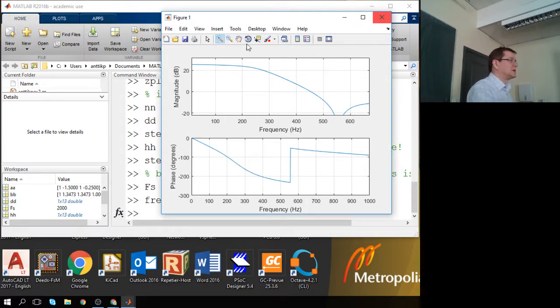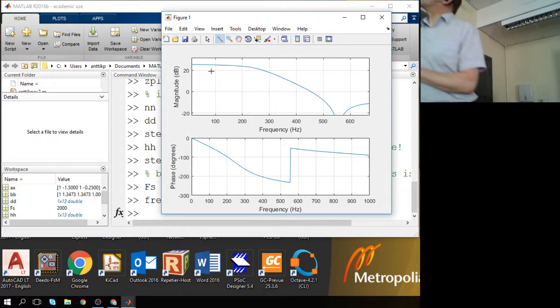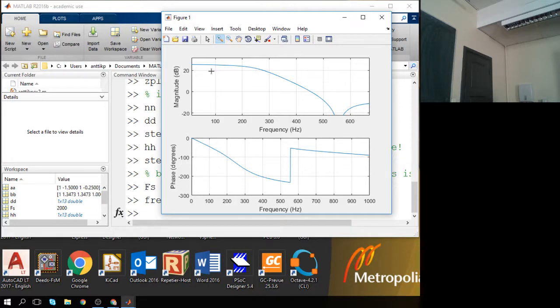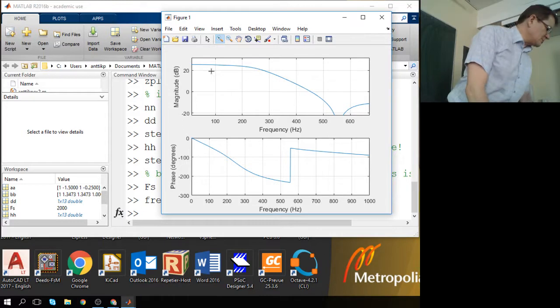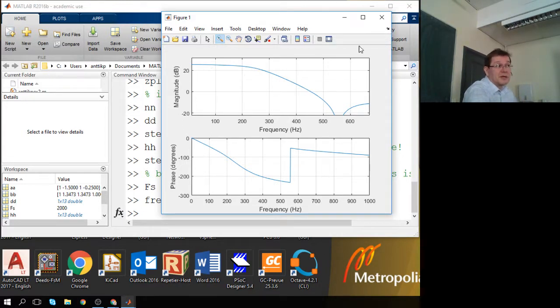Okay, good. One small detail here on the frequency response. Not a unity gain system. So we have an amplification also there. Most of the digital signal processing filters are made for unity gain, and that actually is very simple to make. We just calculate the current maximum of that frequency response and divide parameters B with this value.